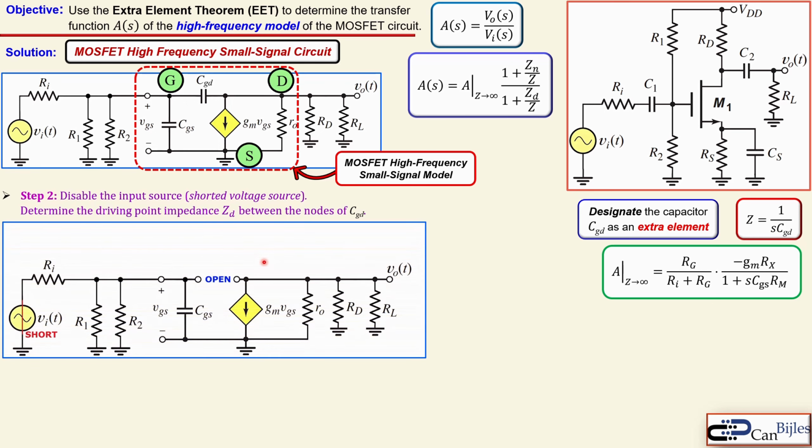So let's bring the small signal circuit again. You see the shorted input voltage. This is now a wire. Since this is a voltage source, it will be a current source, then it will be an open circuit. Okay. This open connection, I will now look inside that. And again, bring up our shorthand notations. And I will now look in that and I will determine our ZD.